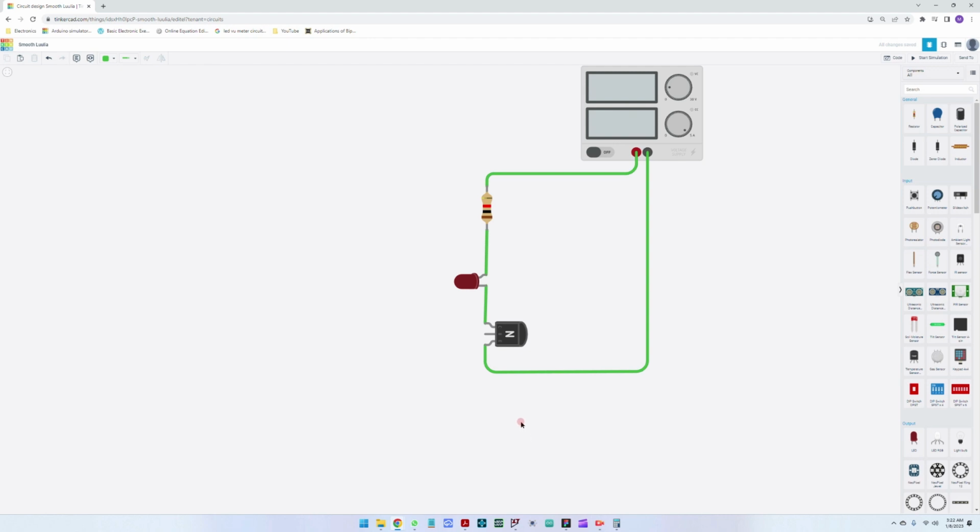The next step is to give a command to this transistor. The transistor creates a switch between the collector and the emitter, and now we just need the command signal. So for the command signal, we are going to take a resistor and place it in the base of the transistor so that we limit the current to the base of this transistor, so that we don't break it.